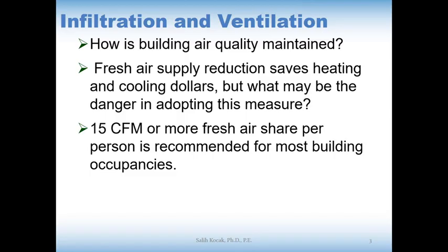So in those places the fresh air intake is around 40 to 50 CFM, and depending on the location and the number of people, this number is subject to change. However, again, this is the minimum required CFM per person to provide enough quality air.